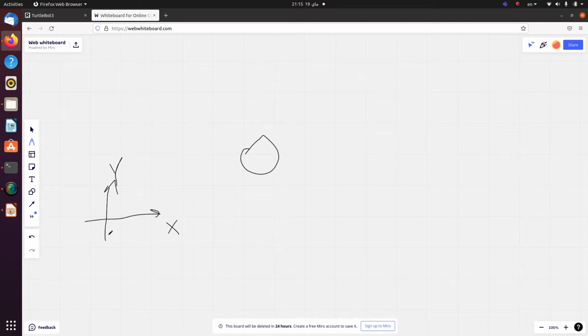Of course, that's not the case for other mobile robots like drones, for example quadrotors, which have variable height depending on the thrust of their thrusters. The same thing goes for autonomous underwater vehicles or remotely operated underwater vehicles, which have 6 degrees of freedom underwater, unrestricted. And there are also many other types of robots. We've got humanoid robots, for example, and actually their center is always oscillating in a sine wave fashion, because the center of mass follows a sine trajectory or an almost sine trajectory during walking.